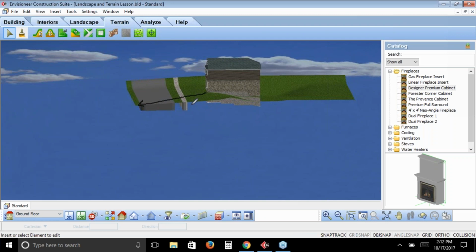And you'll notice that as the terrain has changed, the paths that I put in, this roadway and this sidewalk, both were put in using our paths tool. So just picking points to show the thickness, the width of the path itself, the material, and then showing its start and end point.